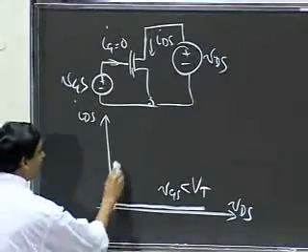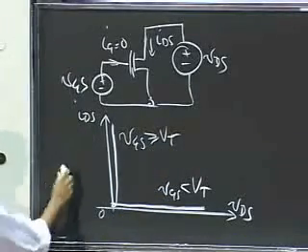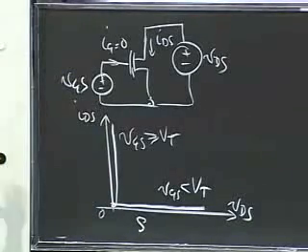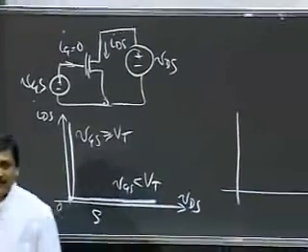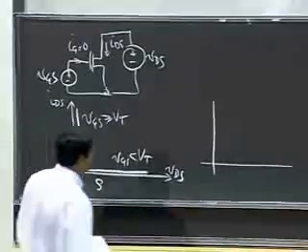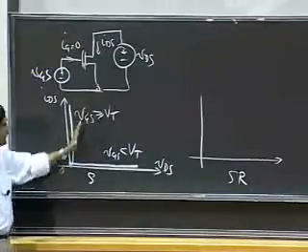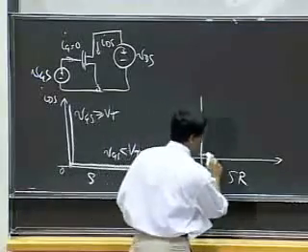And when VGS was greater than VT, the switch model of the MOSFET simply said that we can model the drain to source as a short circuit. You saw this in your labs, and you saw that it was a very small resistance between the drain and the source, and it kind of looked like a short circuit. But then we said that's not quite it. There is some resistance, and so a slightly more accurate model would have this line droop a little bit to imply that there was some resistance R on between the drain and the source.